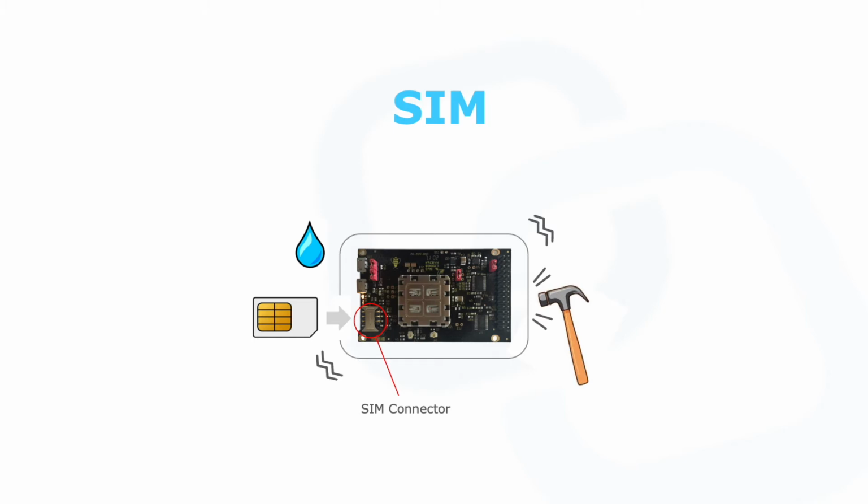This connector has some spring-loaded contacts, which make contact with the electrical plate of the SIM card when inserted. This allows the device to communicate with the SIM in order to get the device onto a mobile network. The problem is that in some IoT environments, for example in agriculture, the device will endure a great deal of vibration and instances of shock. This can cause the spring-loaded contacts to disconnect from the SIM card momentarily, causing problems with the device.